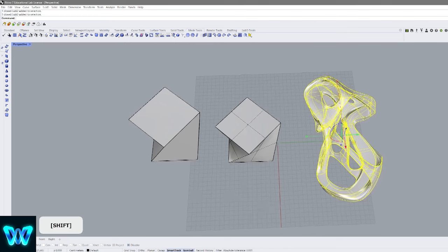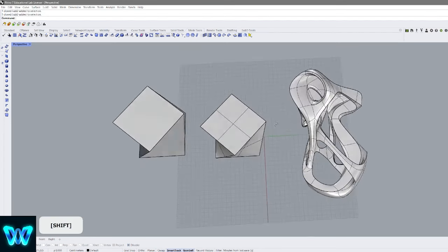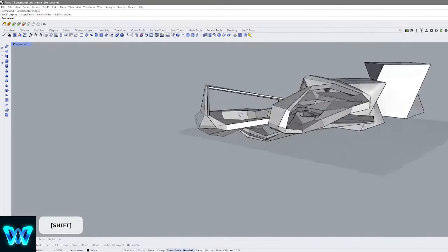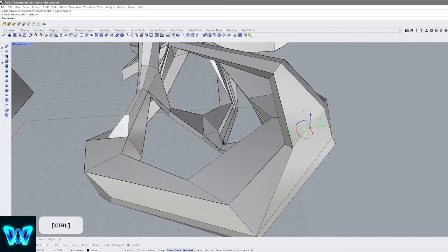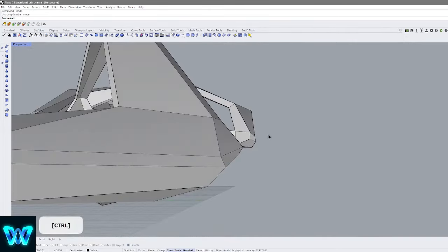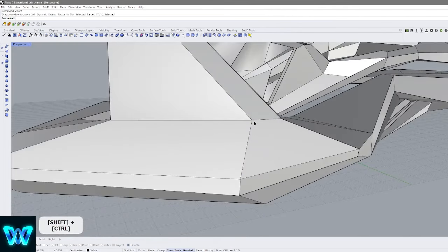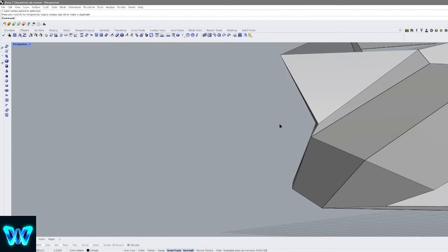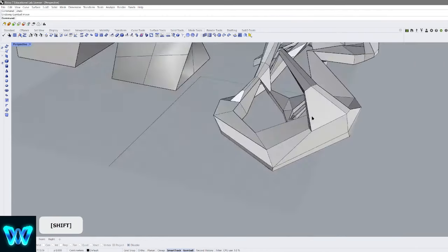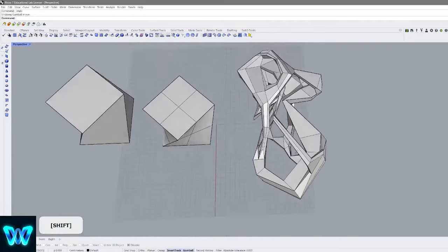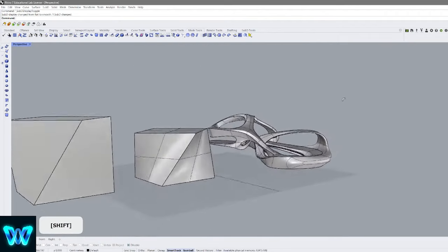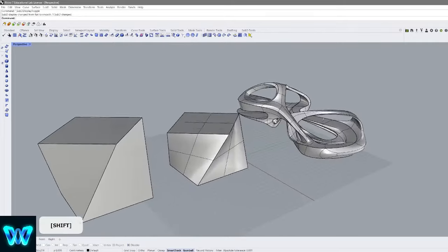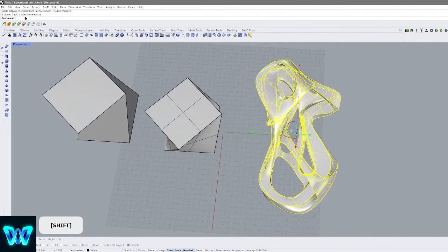So in this case, we're gonna work with SubD, and SubD in theory is a representation of a mesh, but it's just automatically being subdivided for you. If we press tab as we're looking at it, now we're gonna look at its polygonal mode, and in this case, this technically works exactly like the mesh. As I was mentioning, the faces don't really bend with how you move it. So if you look at the face right here, the face is not really bending, but the moment I press subdivision, it creates a curve because it starts to subdivide every polygon, and it creates a smooth version of it. If you were to use this in Maya, you would see it showcased clearly, how a mesh is being subdivided. But in this case, Rhino makes it its own type of polygon.